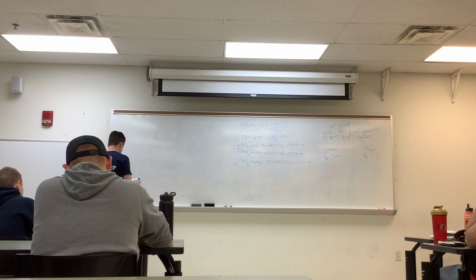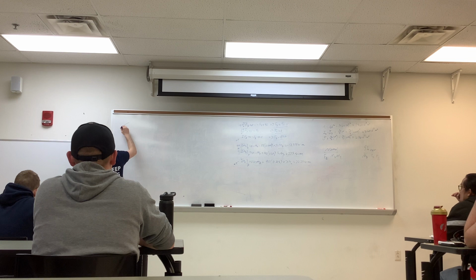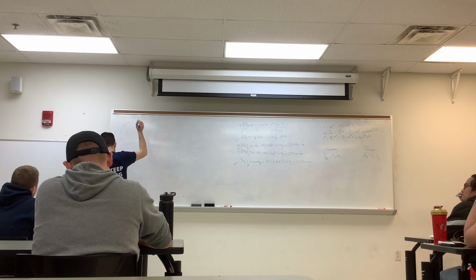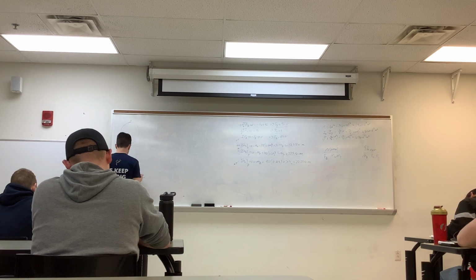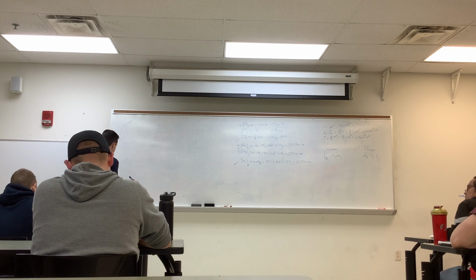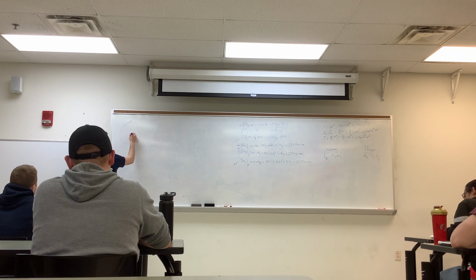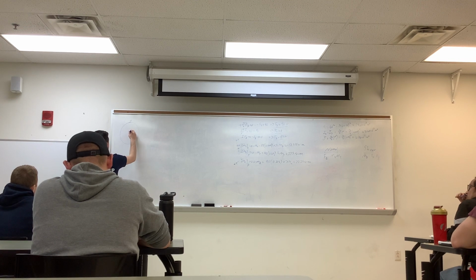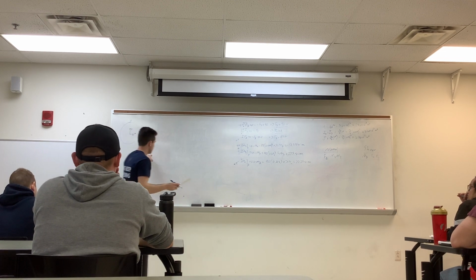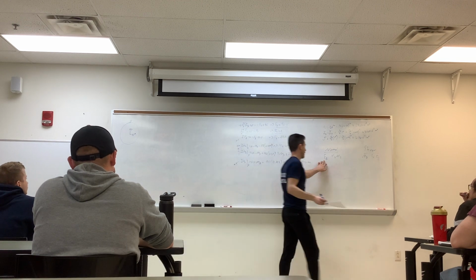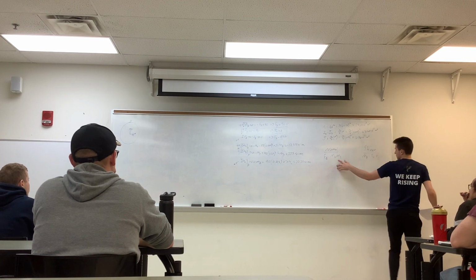So our cross section with regard to point H. So our circular cross section, point H is here, and then our x and y axes from the diagram. So we had our x-axis, we had our y-axis. So our equations that cause normal stress, a combination of our axial force and our moments about the x and about the y.